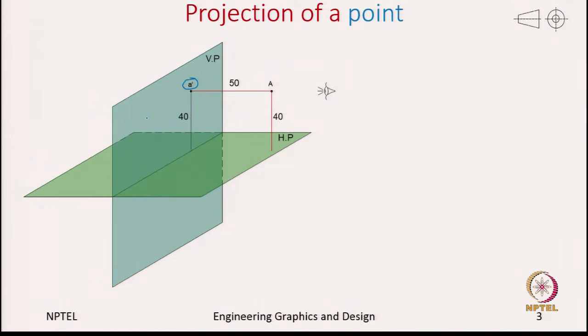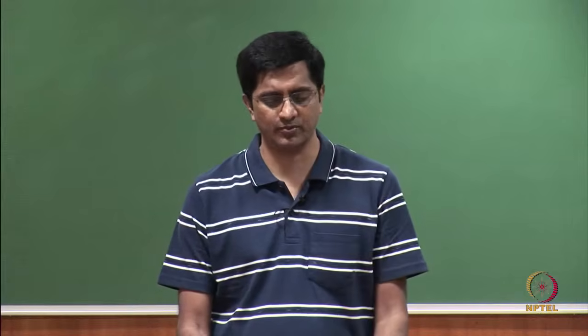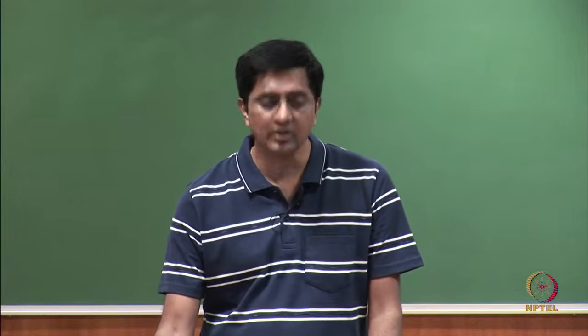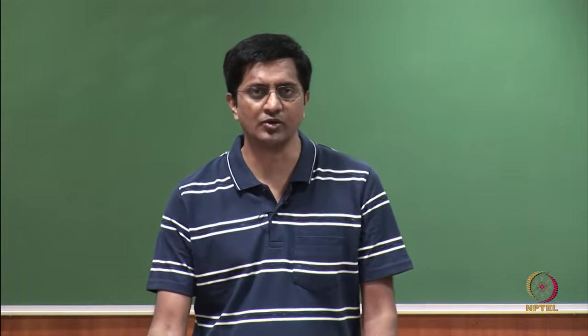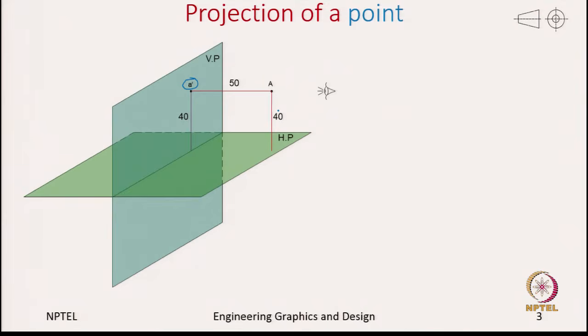Similarly, okay. So, a very important point now is we are discussing orthographic projections, where the projectors are normal to the projection plane. The reason why these orthographic projections are very important is because, as you can see previously, we know that the point A is at 40 units from the horizontal plane, and even in the front view, the point A prime is at the same 40 units from the horizontal plane.